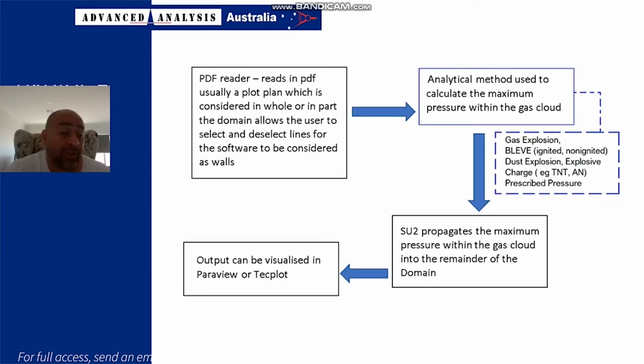It's run in a 2D fashion. This is deliberate because SU2 can run in 3D, so you can configure SU2 to run on detailed 3D geometries. There's no need for that, and in fact, CFD software has traditionally been dissipative for explosions. So to not be on the under-conservative side, SU2 is configured in a 2D simulation. So you're basically solving at the ground level.